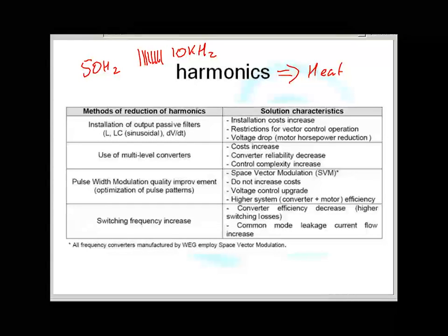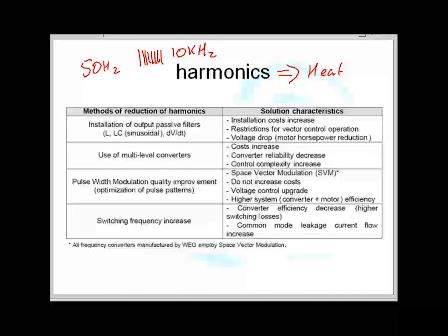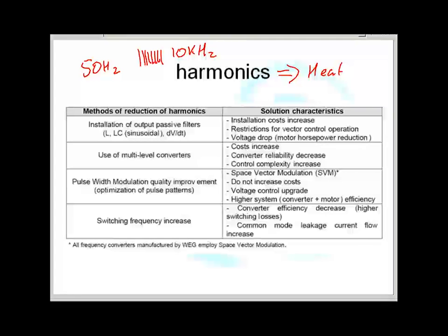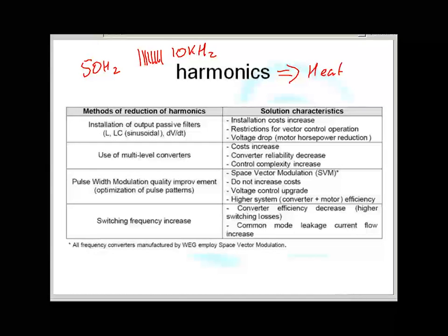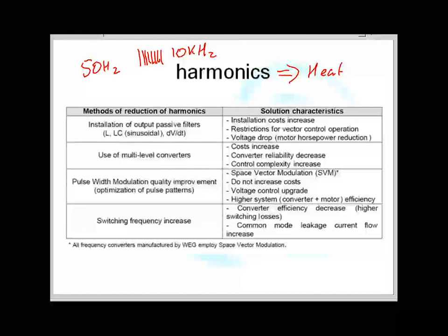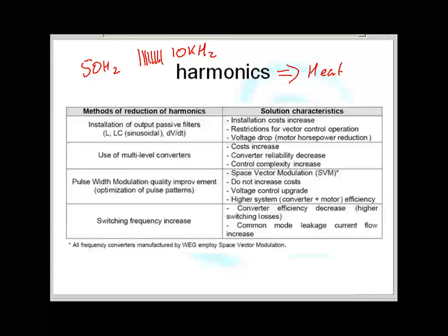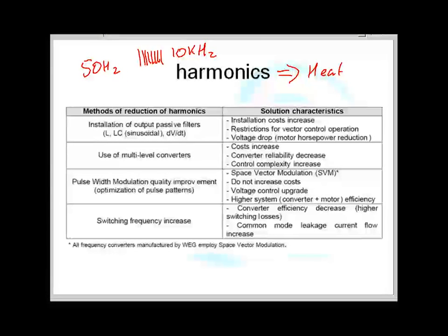Put simply, you put energy in and you get energy out. If there's any difference between the two, that's going to come out as heat. And what's been found is that as you reduce the frequency, there's a bigger and bigger difference between the energy you put in and the energy you get out. The torque is reduced, so the heat increases, because that energy has to go somewhere.